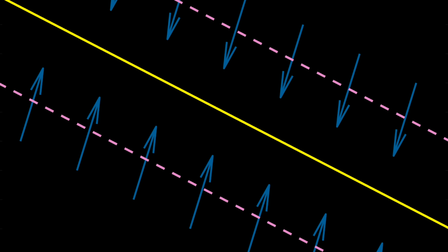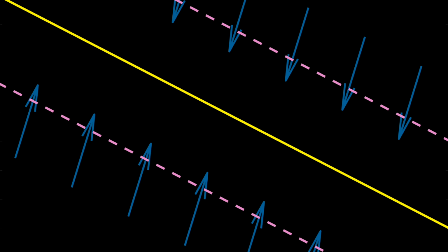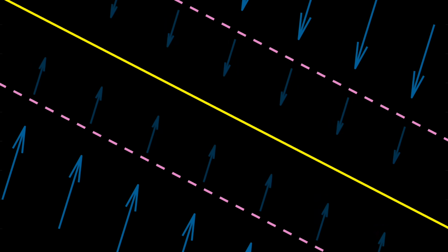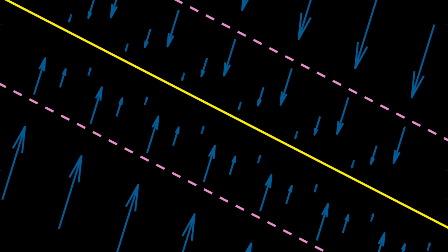For example, one type of boundary layer option is saturation, where outside of the boundary layer you use full gain, but inside, the reaching law gain is proportional to the distance to the surface. In this way, as long as the system stays within the boundary, the control is smooth and the chattering is reduced. And it's only when the state nears the edge of the boundary does that heavy gain really come into effect and try to push the state back.